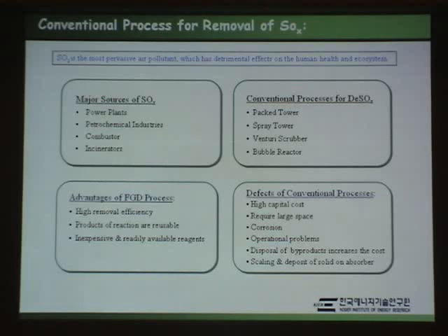But on the other side, it has some limitations, like it requires high capital cost, larger space, corrosion, some operational problems like flooding, foaming, entrainment, and disposal of byproducts also increases the cost, scaling and deposit of the solid on the absorber and the downstream equipment.